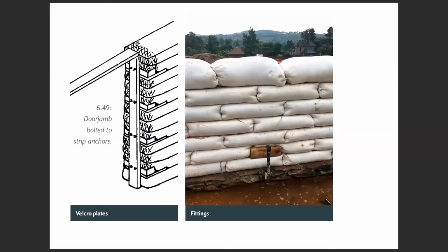So it's very important that you allow for areas where you're going to hold windows, doors, electrical fittings, anything that you're going to hang on that wall. There are timber pieces that you build within, and they are pressed with the weight of the bags, so that you can easily screw a door, a window, anything there without any risks.